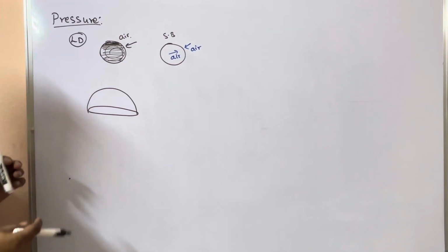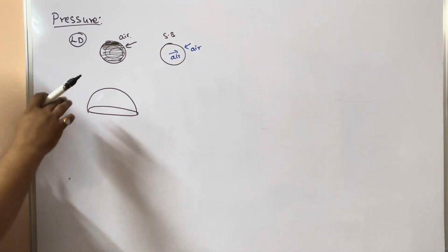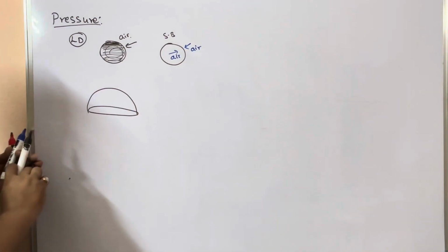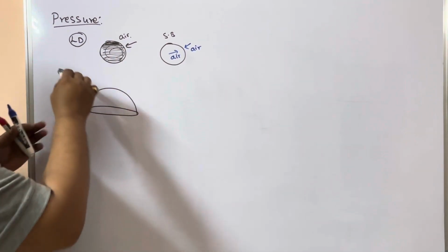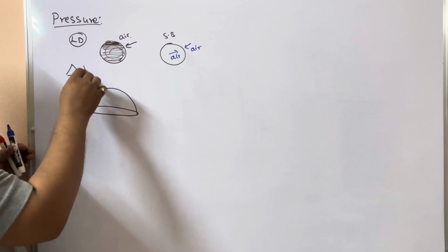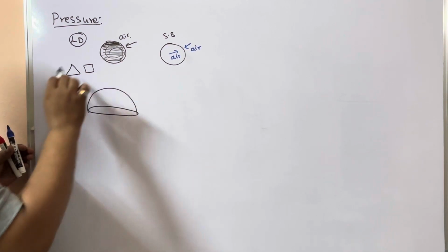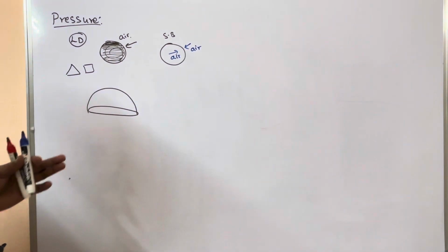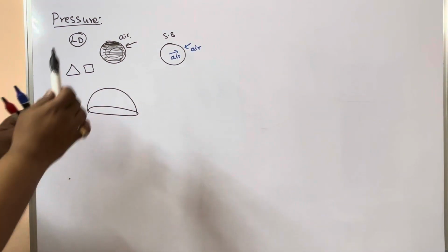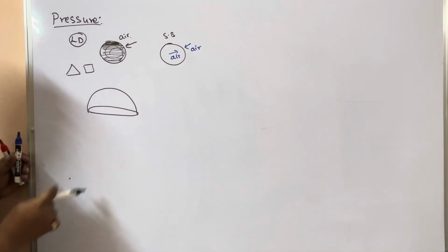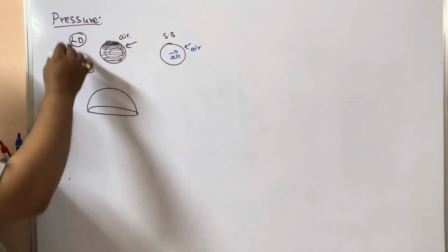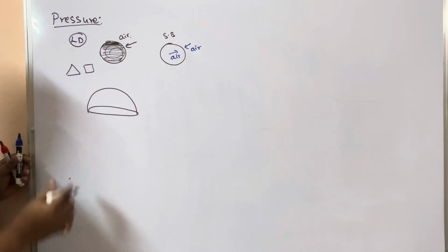This liquid drop is forming because of surface tension. For a small volume of liquid, it is going to acquire only a spherical shape, as already discussed. Why won't it gain a triangle, rectangle, or cylindrical shape? Because the sphere has lesser surface area and smaller volume, because of surface tension. Now two forces are going to act on this: one is due to pressure, another is due to surface tension.